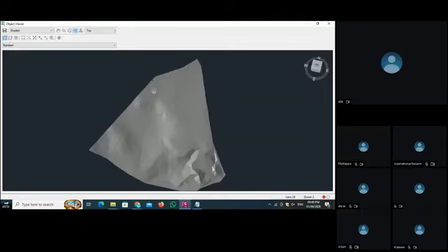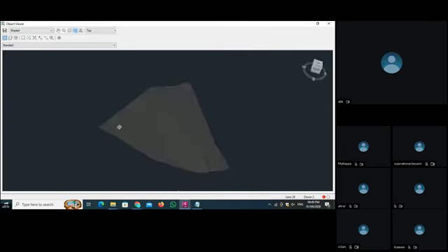See, I select all points, and our ground shot points are coming from here to here. So if you created the contour with the help of the ground shot points, then you create the contour from here. This alignment line is extruded. Our contour is created very well.